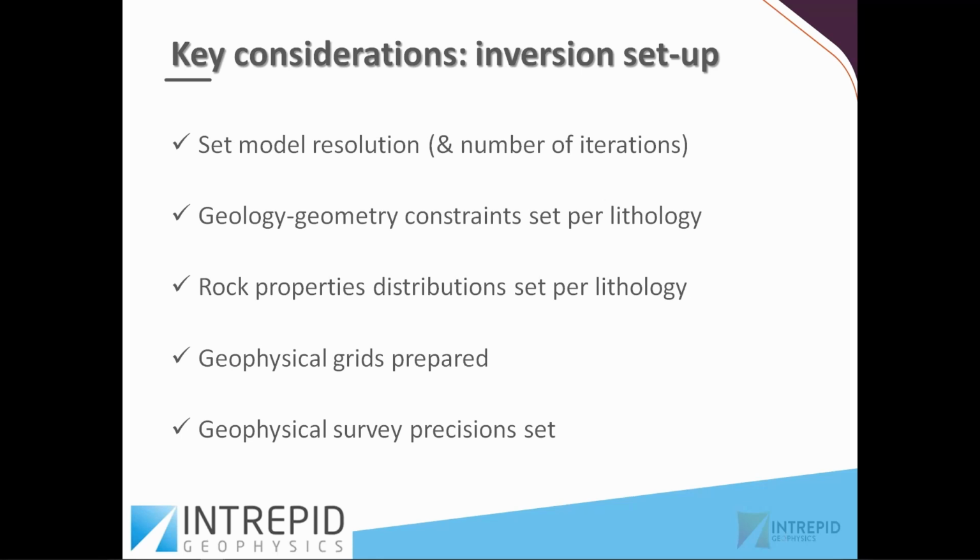Your data cell size will be resampled during the inversion operations for a comparison basis, to compare your computed response with the observed. It is not required to select the discretization cell exactly the cell that you actually have in your observed data. You can select any cell you want.